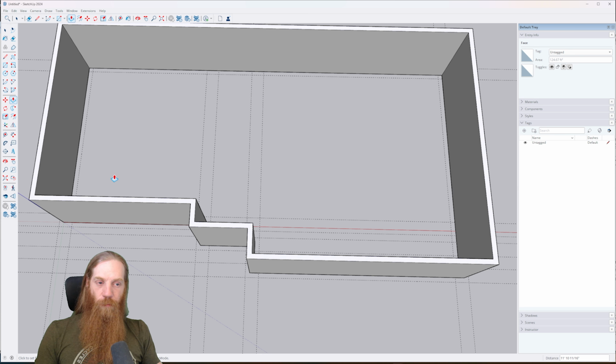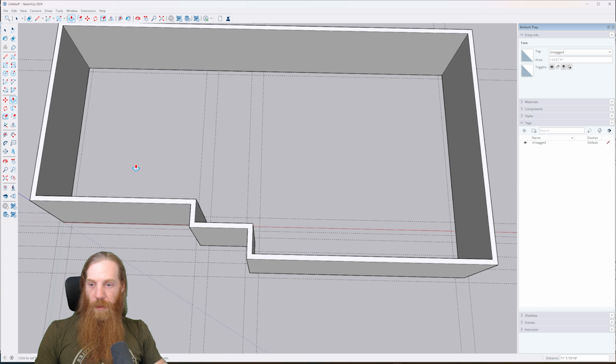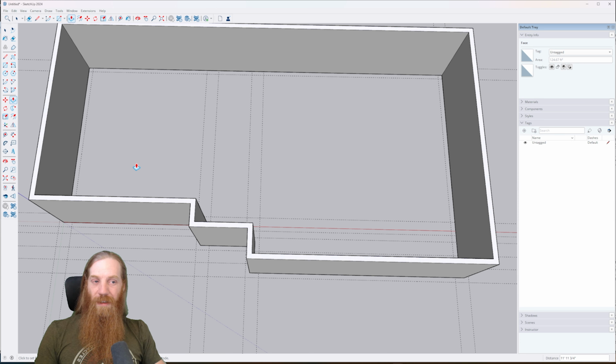for it. It really makes the basement way more livable, feels way more comfortable, and just will get you a higher value on that home. It's well worth the extra cost, in my opinion, but that's a personal decision for your budget. But if you can, I would go with a 9-foot ceiling. 10-foot ceilings are really nice, but they can often feel a little excessive. Your excavation at that point is going to be getting pretty deep probably. So I feel like a 9-foot ceiling for a basement is a nice sweet spot for most homes.